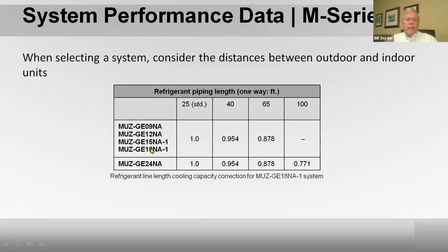So let's take this 18,000 for example. If you look that particular model up in the catalog, there's a newer model that's a -2 or whatever. It's actually rated 18 now, but this particular model number in the catalog, that 18 is 18,000 BTU nominal capacity, which actually in the book, the rated capacity was 17,200.